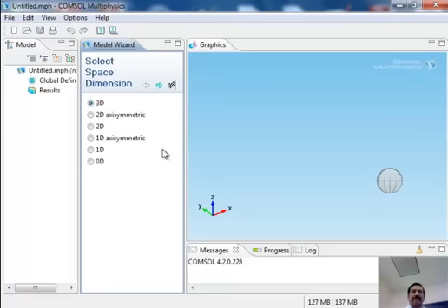If it is in one dimension, you will select 1D. If it is in 2 dimensions, you will select 2D. If it is in 3 dimensions, you will select 3D. The 3D could be you're designing a furnace in a plant, and you want to determine the heat transfer from all the furnace walls. So it's a 3-dimensional object. CAD will help you in importing the actual geometry into this program, and then you'll specify the differential equation and the boundary conditions. I'm going to do just 1D because I have only a fin in 1 dimension. It's an ordinary differential equation.